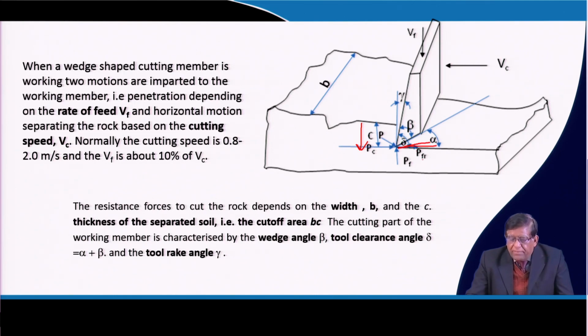That is exactly, it is very small or it can be even smaller. Then what will happen? When there is no clearance, that means there will be more rubbing action, more friction, more heat generated, and more tip damage will take place. So, there is some impact of these angles on the way it will be cutting and the way this tip will be performing.